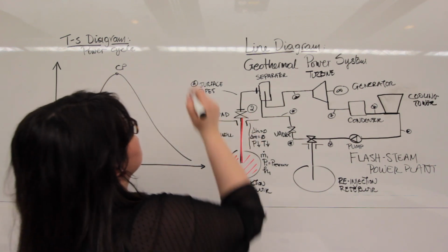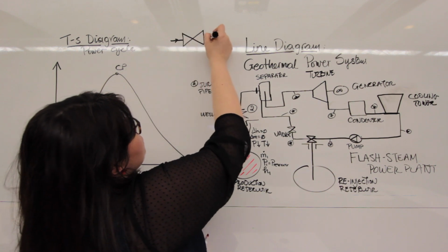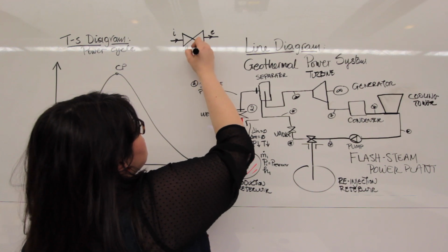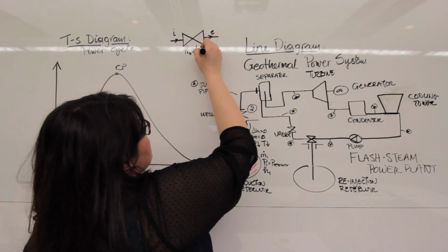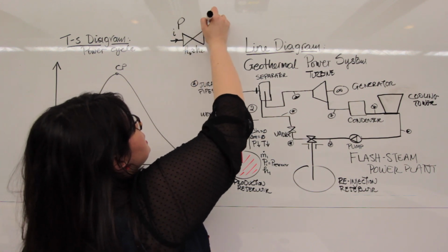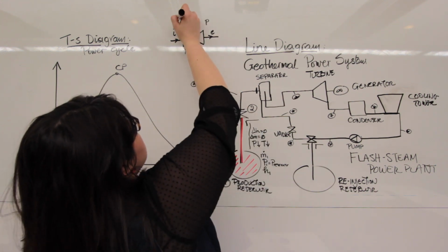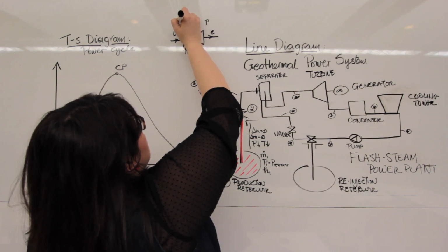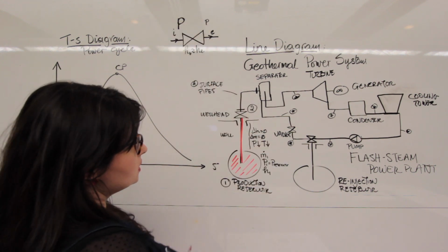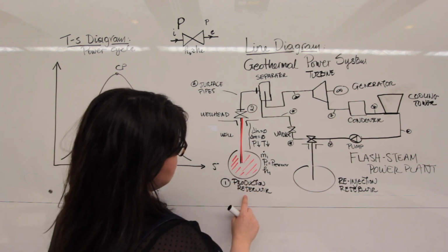Wellhead, that's a valve. I have a valve. The main thing that applies in terms of assumptions, if this is the inlet and this is the exit, is that H at the inlet will be almost equal to H at the exit. At the inlet, I will typically have a large P, and at the exit, my pressure will expand and I will have a smaller P. Okay, so my pressure will drop. Similarly, I will also have a small drop in temperature, although that's more negligible.